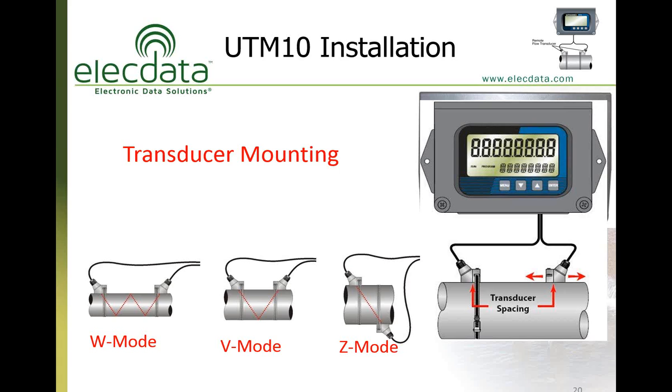Now, depending on the pipe diameter, the software or the UTM10 meter display will prompt you to install the transducers in either a W mode, a V mode, or a Z mode configuration. The W mode is typically on smaller diameter pipes, so you get basically 3 reflections through the pipe before the signal is received at the other transducer. In a little bit larger pipes, you can use a V mode, where there's just 1 signal reflection off the wall of the pipe before it hits the receiving transducer. And in very large diameter pipes, we use a Z mode configuration, where the sensors are on opposite sides of the pipe.